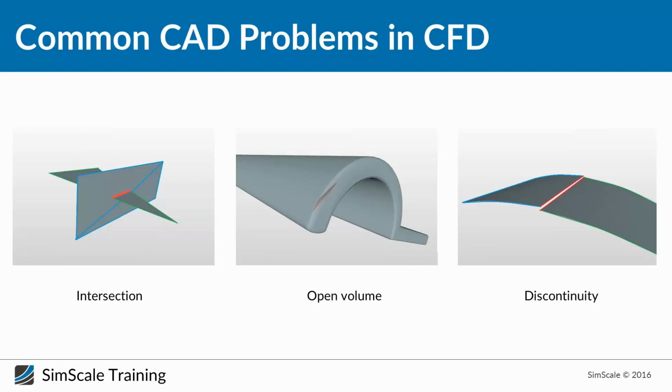I'm going to put it as a note, and I'm going to talk about it later when I get to the picture of the front wing, where you have to take the intersection into consideration, because the mesh generation algorithm cannot really understand which surface has to be meshed and which has to be cut. Like I said, sometimes it's important to have intersection.